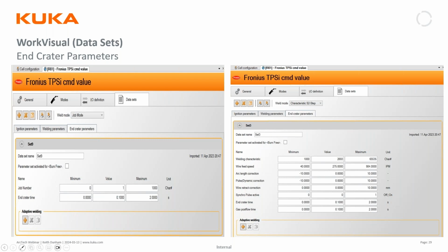And then you say, what signals do we have access to map to I/O? So as long as our device talks to whatever that device is and that is giving us signals back and forth, you can map it to that I/O. So let's say, for example, you have a gas sensor or a wire runout sensor. You could map that into the previous page of this, and you can actually set limits and things to say, if you see the wire runout, do not move on to the next weld, because I know I'm not going to be able to finish it. So yeah, thanks for the question.